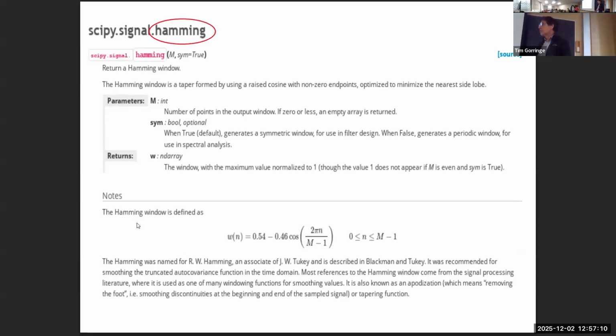So we're going to use these two here. And again, I won't go through the arguments. The arguments are pretty simple to these Hann and Hamming functions, but we'll just go ahead and use them and implement them. So this means that with the convolution function for all our windows, with Hann and Hamming functions for our particular windows, most of the work is done for us. We've just got to embed those in the calculation that we want to perform.